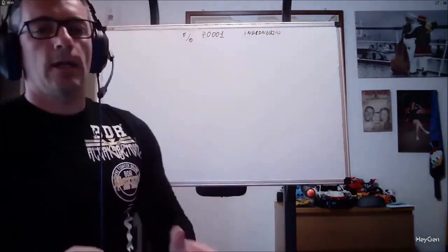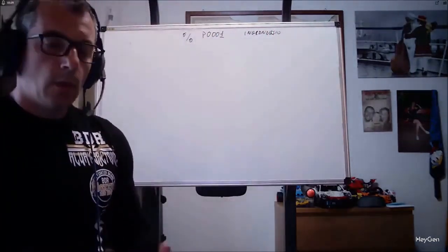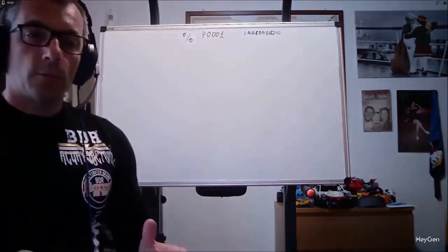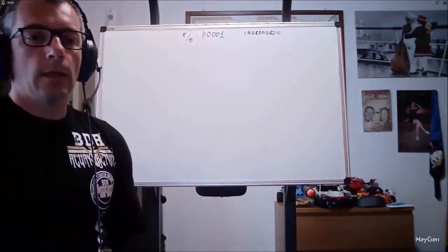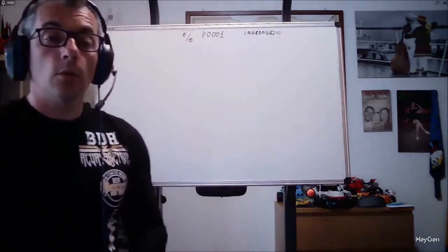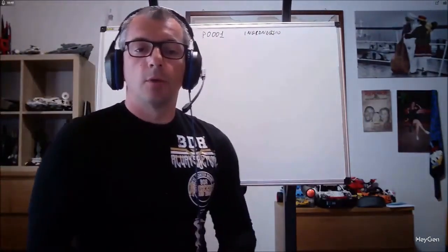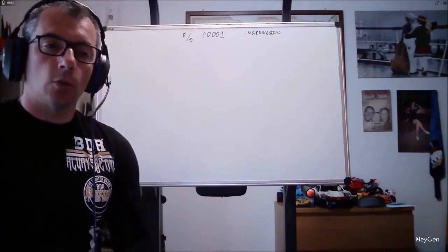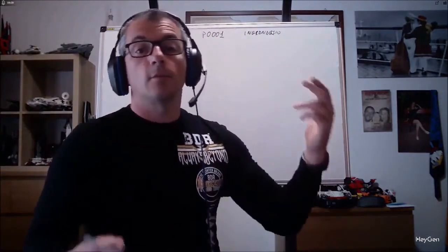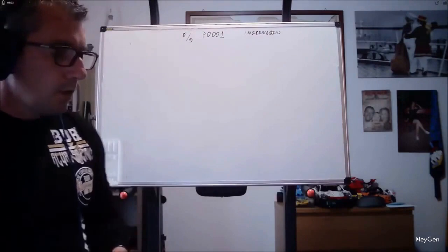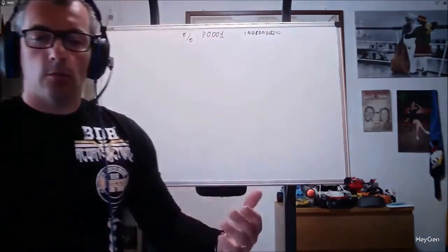I always recommend commenting the first line of your program in the most detailed way possible. So I always include the name of the client, that is, to whom I will sell the part, the code of the item, and if there are any specifications, that is, design modifications, I include those as well. And normally when a drawing undergoes a modification, for example, we have a ring with an external diameter of 100 and an internal diameter of 40 that is then modified to an internal diameter of 45, it becomes specification B. I copy the program, make a copy, and keep the old one, just in case they ask for a replacement. After that, we need to start communicating with the lathe.